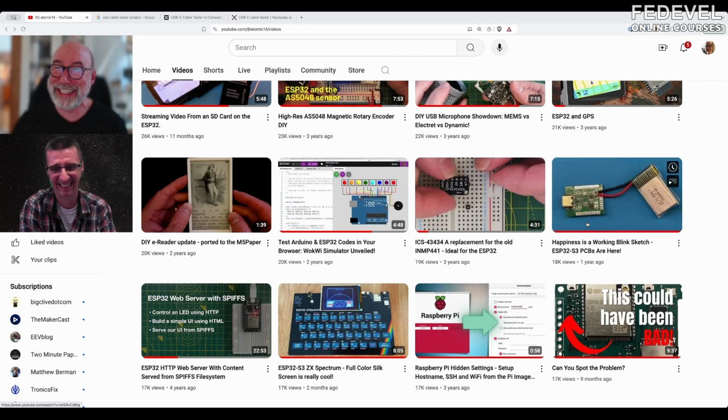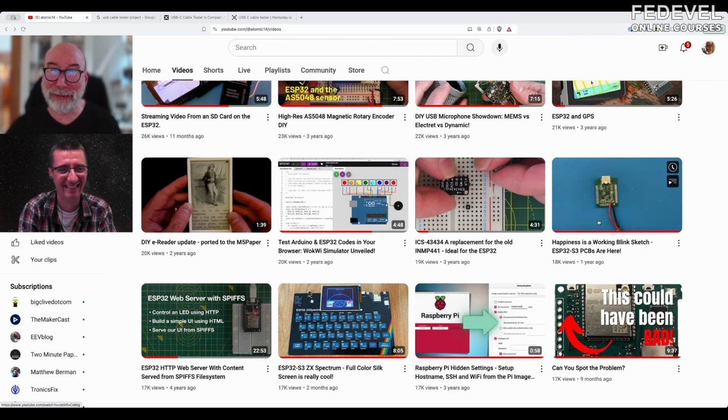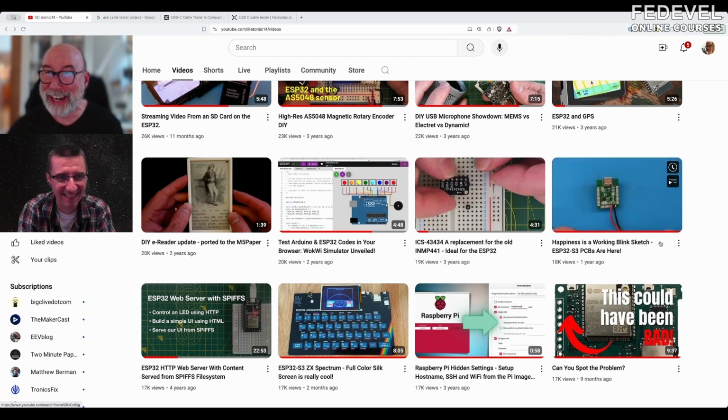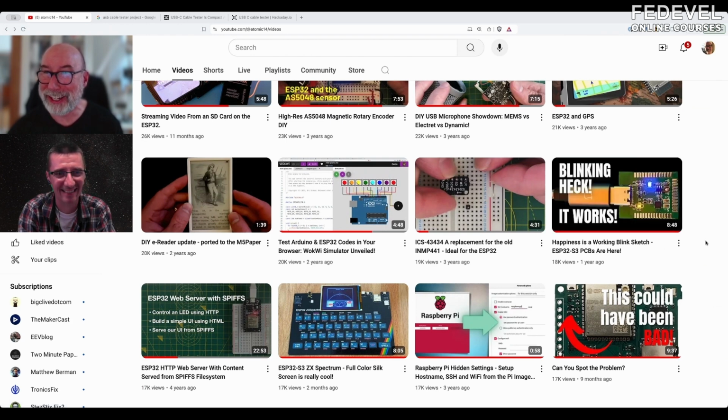Yeah, and it was a really fun project because initially I thought you can't fit enough stuff on the back of a board to do this. But actually there's an audio amplifier, and I think in one version there's a battery charger, audio amplifier, a regulator, and a couple of LEDs. There's a lot of room on the back of an ESP32. So yeah, a little board is definitely doable.